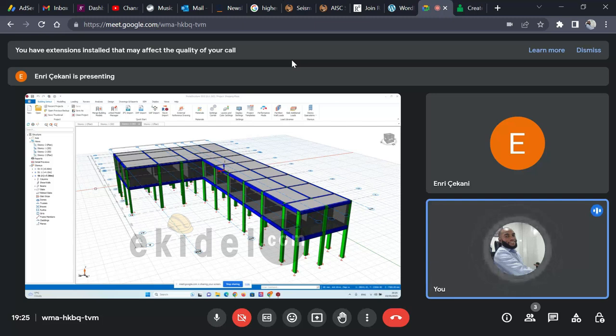When I talk about increasing the strength, it simply means either you increase the size of the concrete section, or you increase the size of your reinforcement. Also, increasing the strength comes into play when it comes to detailing, like detailing a joint between a column and a beam. Those things also talk about strength. Now, for that second option, increasing the capacity of the compression zone, three things must come into play. First of all, you have to choose a good section for the structure, which is the section of the members: the column, the shear wall, the beams, the slab, and all that.